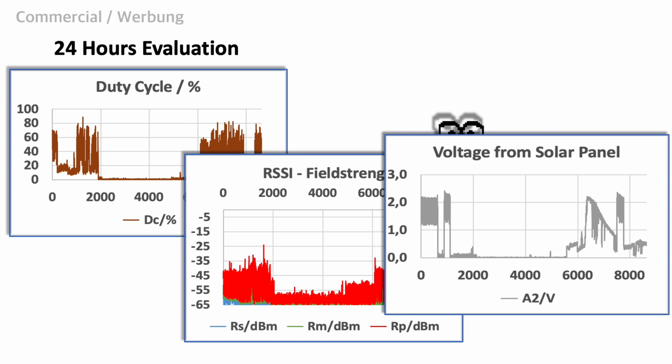With the antenna that I used, we see signals in the range of about 1 GHz to 5 GHz. We measure the physical field strength bigger than -65 dBm of all sources together in the air that we can detect. Of course, we cannot see any content of the signals.